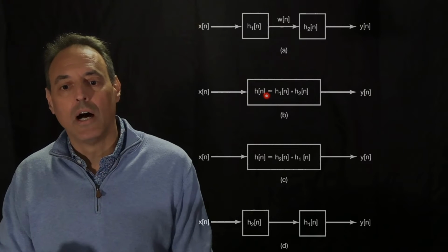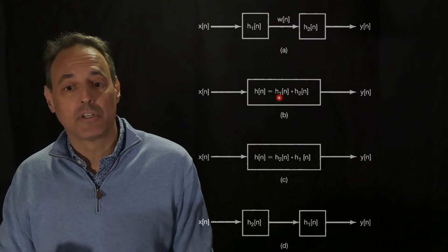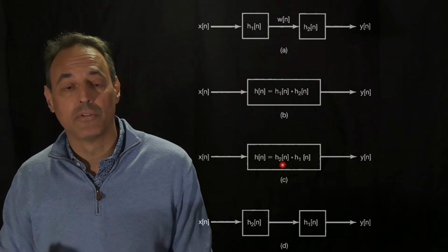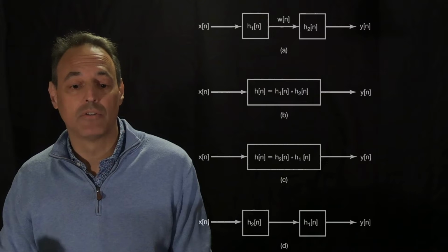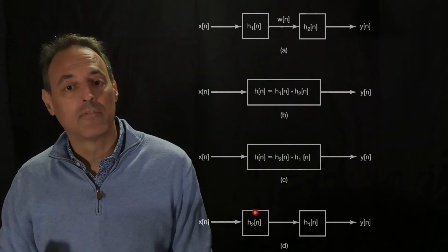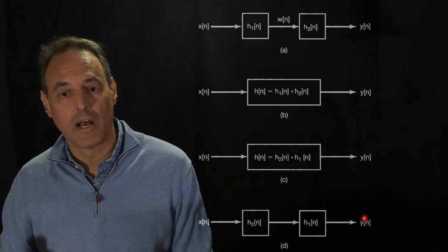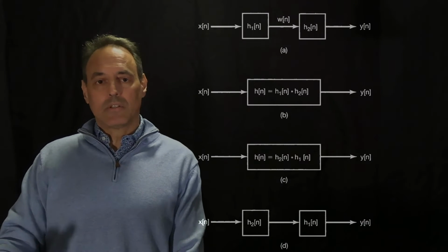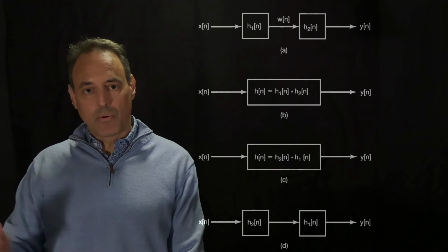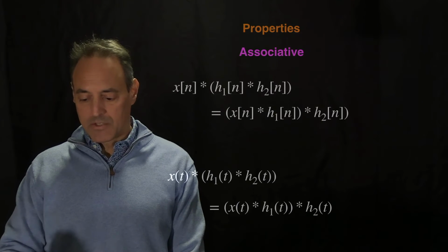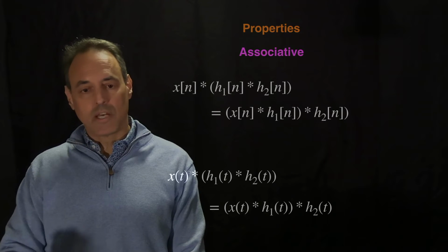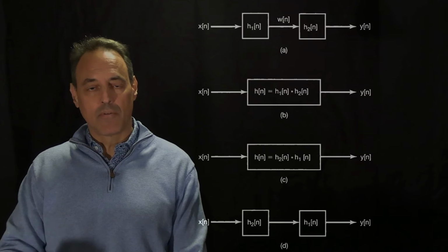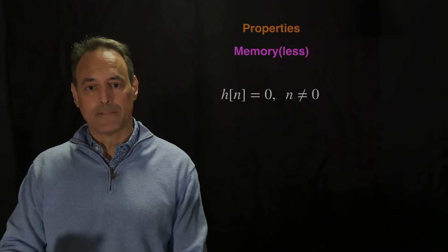function. And it doesn't matter what the order of operation is. In other words, I could do h1 first or h2 second or vice versa. And so I could just reverse those and do h2, h1, and then break it back out into this here, which is x of n. First it gets processed with h2, then h1, then the y output. These are all equivalent. So what it's telling you is that for these convolutions, it doesn't matter the order of operation, right? That's this associative property. These operations, I can do them however is most convenient for myself, whatever's the best way to represent it in practice.